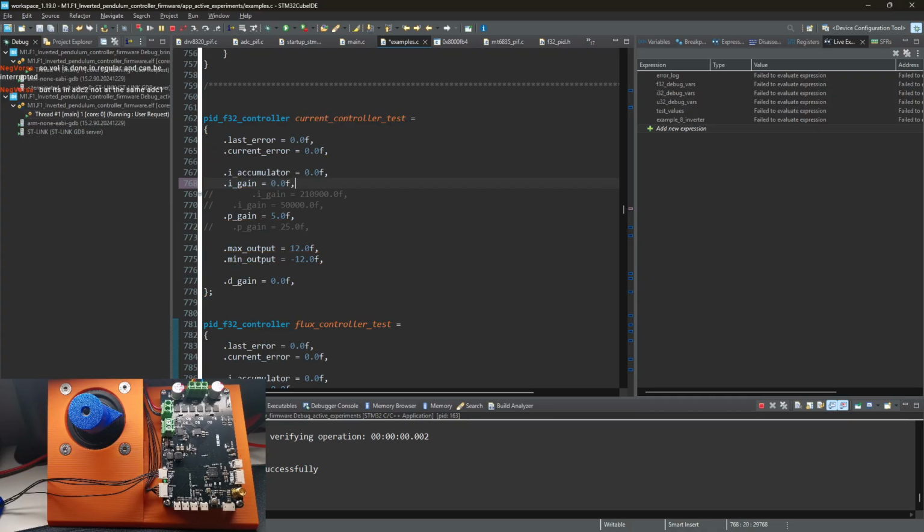It is done, also kind of interestingly. And now I remember why I only use 2 external ADCs: ADC1 handles, like, there is only one regular channel you can have without a need to use direct memory access. And so voltage is measured by one ADC regular channel, and temperature is measured by the second ADC regular channel. So each ADC uses its only regular channel to measure an additional source of voltage. And they use injected channels, which are high priority, to measure currents.